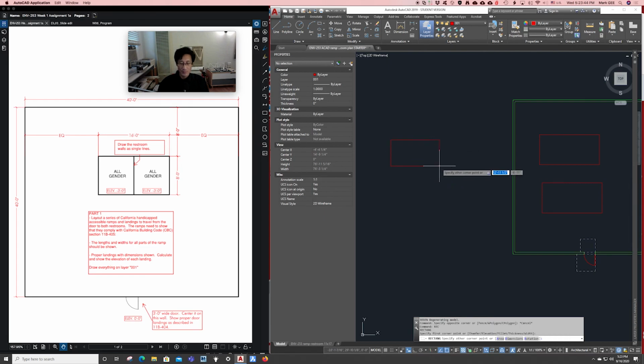Yeah, the zooming did something here with my keyboard. Type at, and you can see that it shows up in the little tooltip where my cursor is, at, positive 16 feet, and then I have to put on a comma because we're entering XY coordinates. 16 feet, comma, and you see after I hit the comma, the little lock shows up on the 16 feet, meaning we entered that X direction. And I'm going to say minus 8 feet, enter.